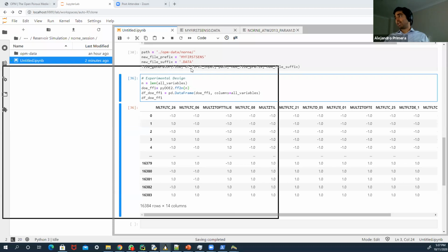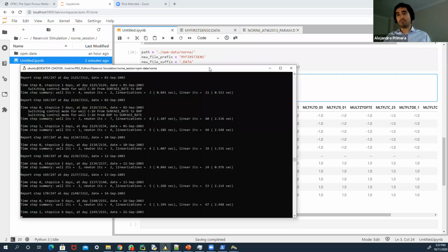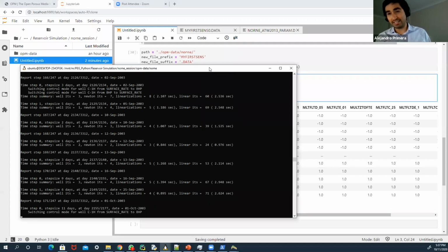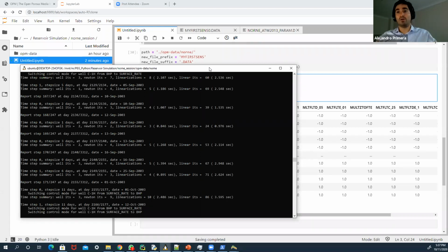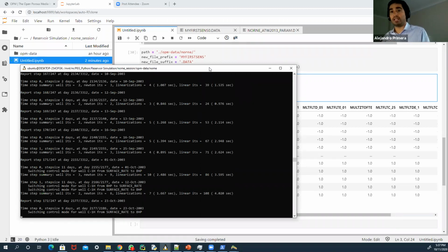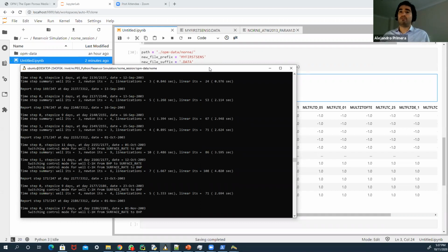In this particular case, let's assume I have only my machine, and I can run 3 cases at a time. When I run 4 cases at a time, I can see that they all start to run slower. There is almost no improvement in speed, or there is a performance impact when I try to run more than 3 cases at a time.